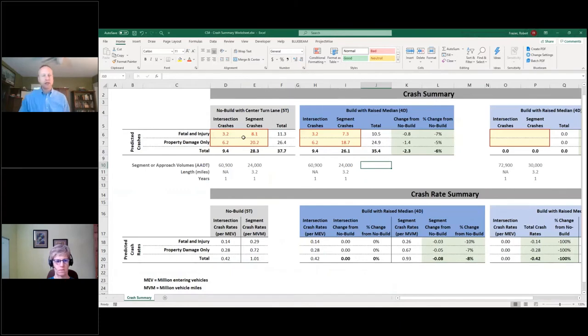All right, so with that information, I'll go back here. We've calculated from that site totals tab the two sets of numbers, and this is just an example. You can summarize this data in a lot of different ways. For some projects this would be more complicated than you need, and for some it would be too simple. But it's a way for us to get our arms around this specific project. We want crashes, crash rates, what's happening at intersections versus segments, and severity. For this type of project, that gives us enough information to start to see where this analysis is leading us.